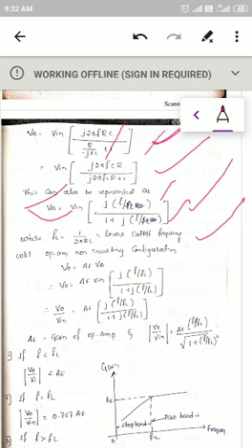This is the potential at the point Va. Now we know that for the non-inverting configuration of operational amplifier, Vo is equal to Af into Va, where Af is the gain of the amplifier and Va is the input to the amplifier. So Vo is equal to Af into Va, which is Vin into bracket of this one, substituting the Va value. Just rewrite it. Now just calculate the gain of the filter.